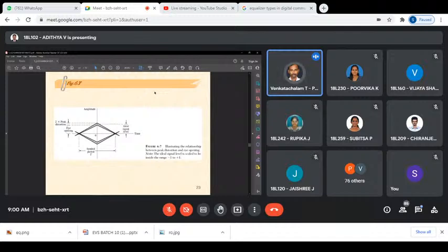You can see beautifully here, I told you about the symbol duration TB: the eye width corresponds to symbol duration TB. And the signal level is not the complete one. It is only for one triangle, not the superimposed triangle.